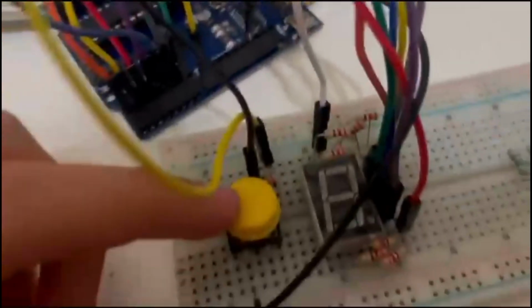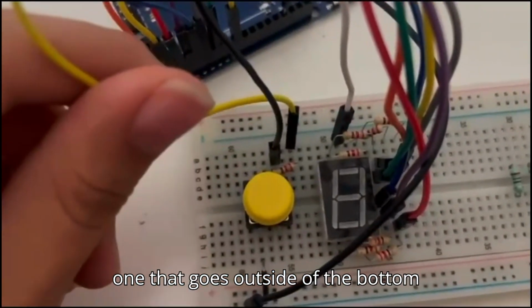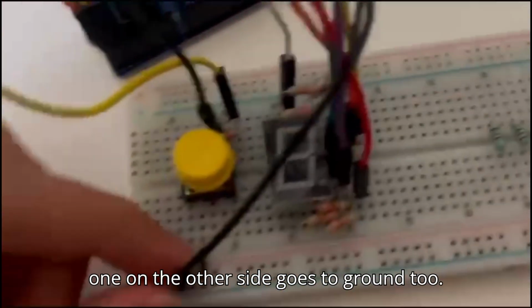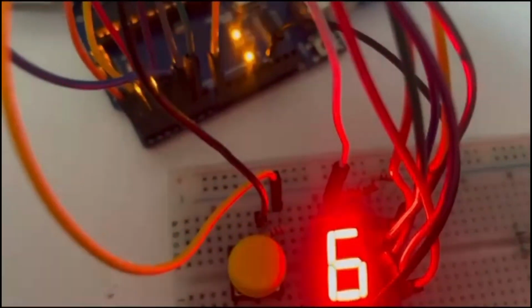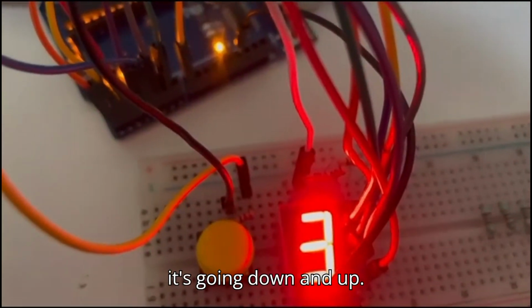Okay, for the button we connect these resistors from this side, and this one that goes outside of the button goes to pin 8, and this one that is inside of the button we connect to voltage, and this one on the other side goes to ground too. Okay, let's upload our circuit. Here we can see it's going down and up.